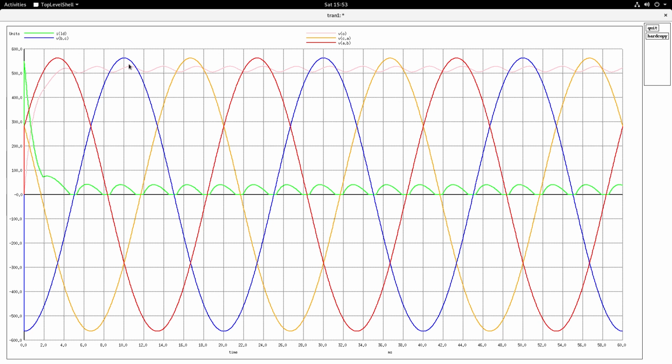You see this drop here is due to the resistive surge limiting. Otherwise this surge would be very, very high. Surge limiting circuits are similar. Even in the case of three-phase, you can use the circuits that we discussed for surge inrush current limiting even here. So after the first cycle surge limiting, you see that it goes into the steady state.